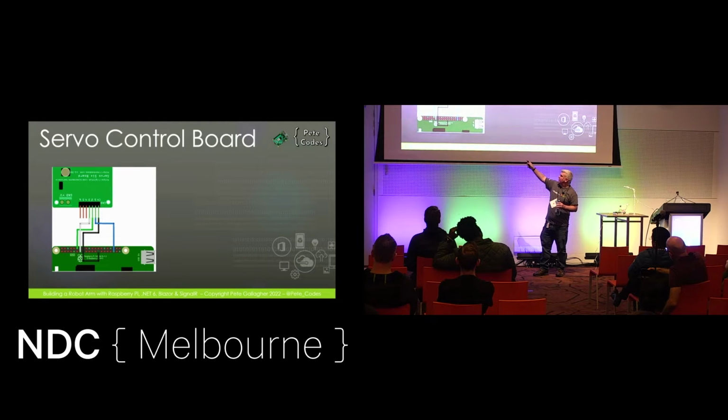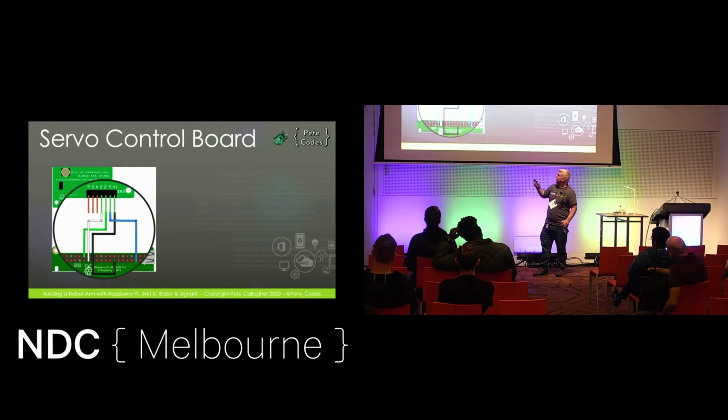So we've got various different pins connected, so zoom in. We've got pin 25, which is ground. Now, if you do buy that Servo 6 board, don't make the same mistake I first made. That first pin is actually ground. When I looked at that pin numbering scheme across the top, I thought that was channel 1. And why is my channel 1 just not working? Because there's no ground. So that's what that pin is doing.